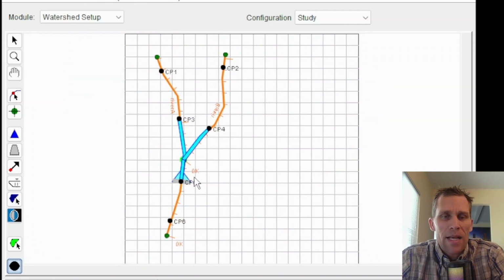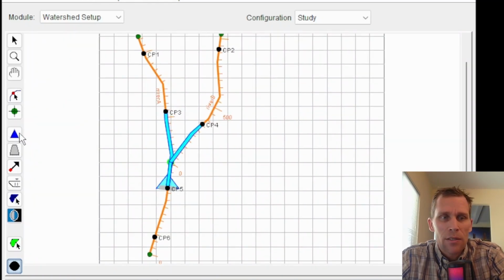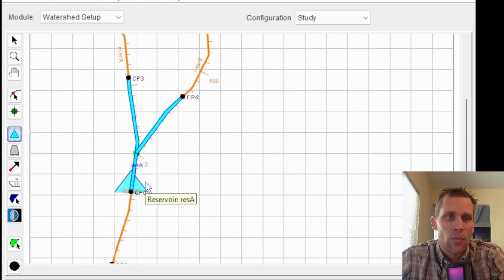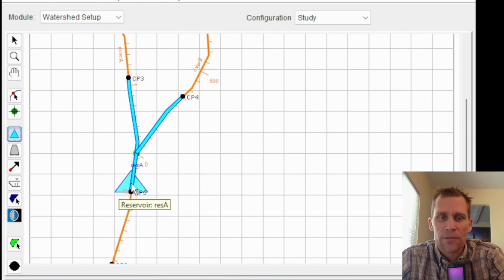Okay. Next, what I may want to do, just to make this diagram look a little bit more realistic, is to click on the reservoir button and then zoom in a little bit if you want. And I want to reshape this reservoir pool right now. So we have the reservoir reach, the reservoir pool. This starts me off as a triangle, and then the dam face here. I don't know if you can see it very well, but it's a very light gray line that's sketched sort of as if it's the dam face. And all of these colors and symbology we can modify, but I'm just going to stick with the default for now. All right, so double click on the triangle itself, and you should see the blue vertex points sort of light up. So now I can drag that around.